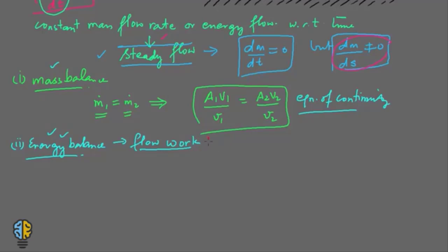because we will be talking about flow work in the energy balance analysis of this steady flow process. Now what is this flow work? Well, if you have to define it, the flow work is significant only in a flow process or an open system. So I'll write it down and you can note it. So flow work is only significant in an open system or a flow process. So this is the very first point.